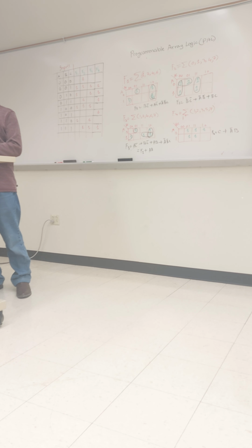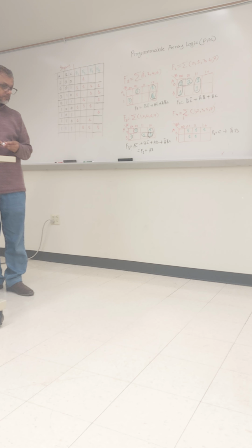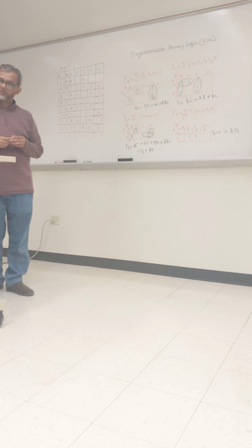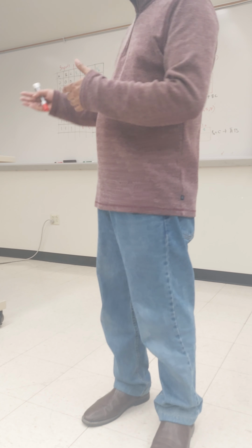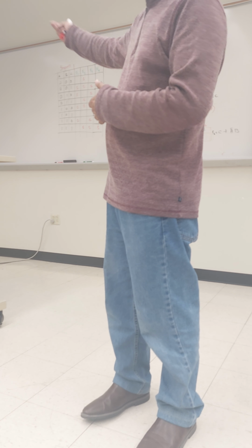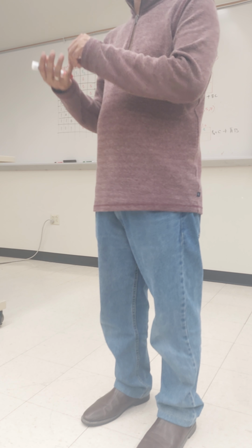Can you explain why we cannot put 4, and in which part of the diagram we cannot put 4? As I mentioned, we have 3 AND gates, which means 3 minterms. Why can we not put another one? We can, but it is possible to implement this using 3 AND gates. Why would you go for another AND gate? Because if you put another AND gate, it will increase power consumption, affect speed, and increase your cost. So that's why. Is it okay?